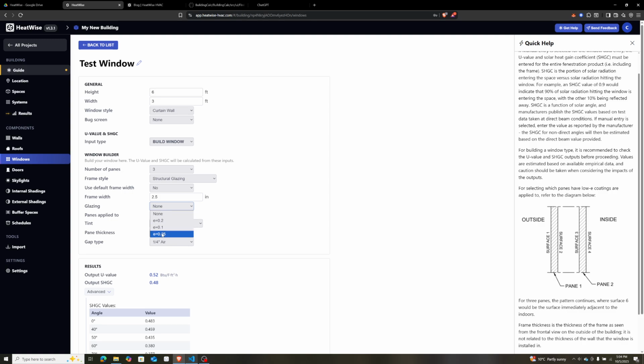And you can see that we omit the 0.4 and the 0.6 options because this is an ultra high efficiency window, and you would never have that high of efficiency without having some really good low emissivity coatings. So the lower the value for this E value, the higher performance the window. So we'll go with 2 panes again, and we'll go with the 0.5 for emissivity.